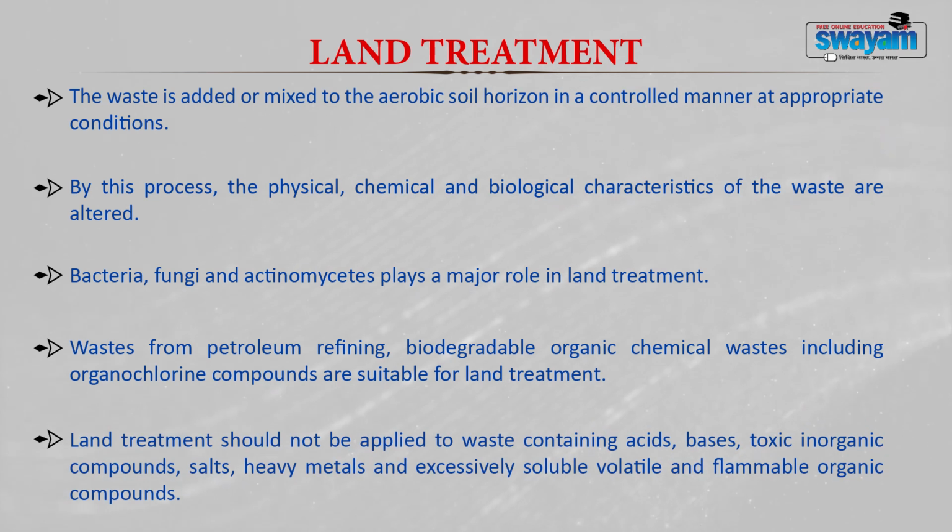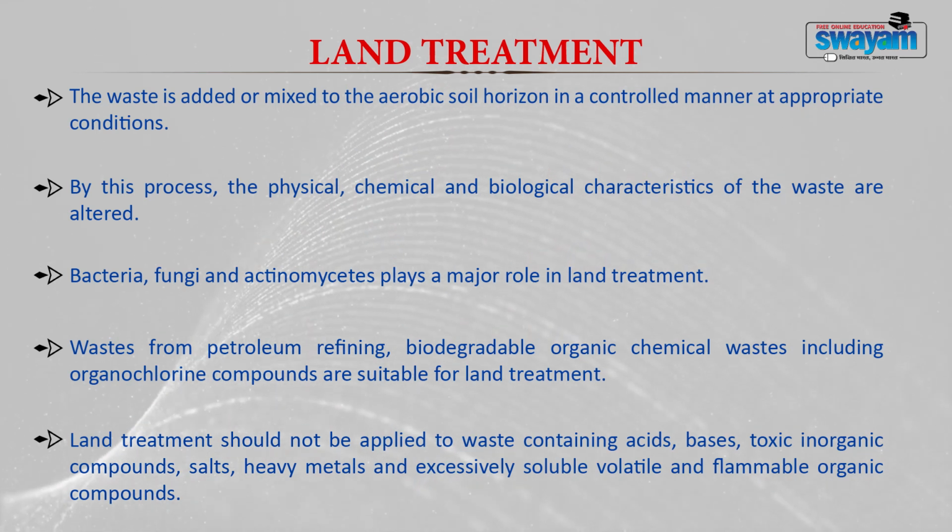Now, land treatment should not be applied to waste which contains acids, bases, toxic inorganic compounds, salts, heavy metals and excessively soluble, volatile and flammable organic compounds.